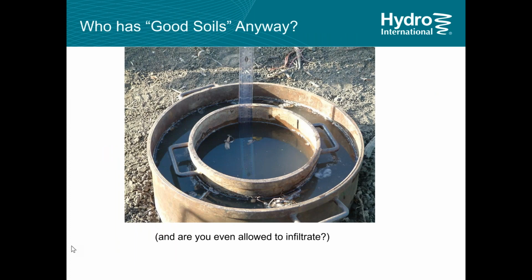Here's a picture of somebody with their infiltrometer trying to find the good soils on their site. Everybody you talk to has difficult soils and is looking for ways to make better use of the land they have. And then beyond that, even if you do have good soils, are you even allowed to infiltrate? There are definitely spots that we've come in contact with where there are protections around groundwater or protections around aquifers. And even though you may have good soils, you're not allowed to infiltrate in certain spots or at certain rates.